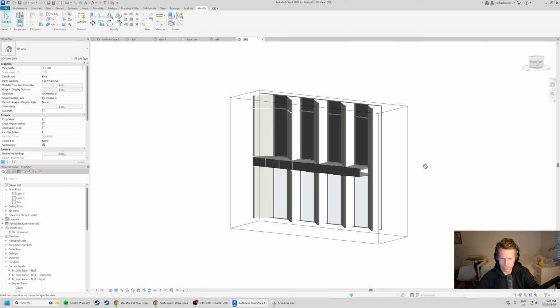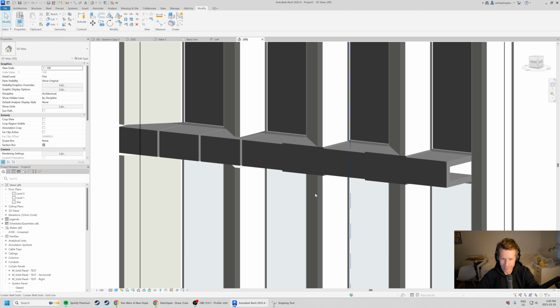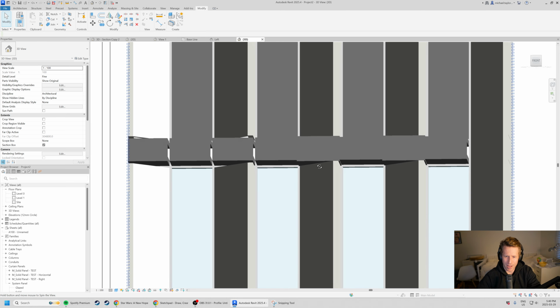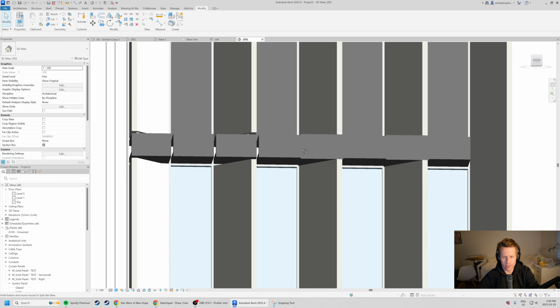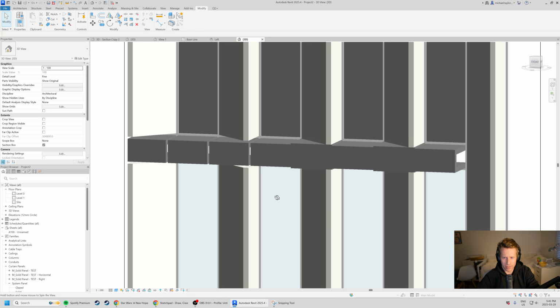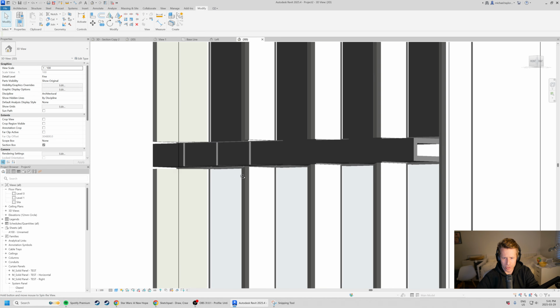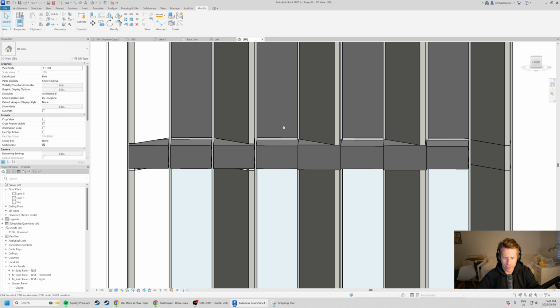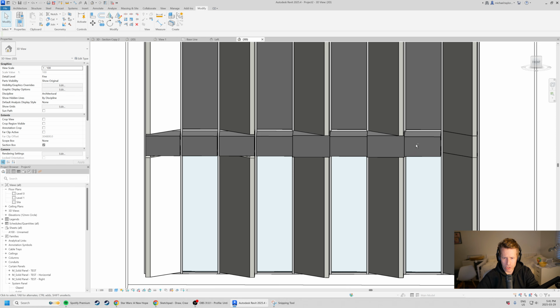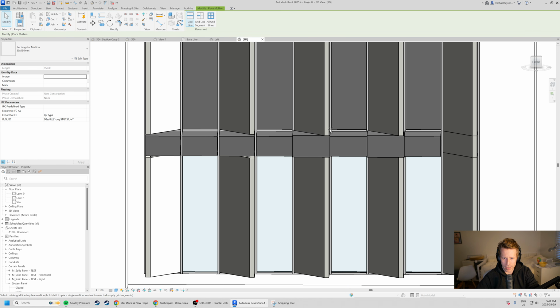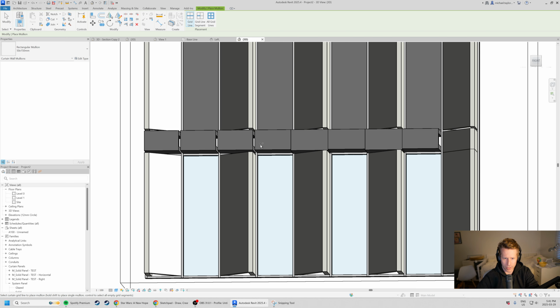So what's going to happen? What's happening right now with Revit is it really wants to see those joints on the edges, because you can see how it's kind of starting to interrupt the flow. So if I come back in here, I'm actually going to go ahead and reattach my mullions, right? So we can kind of have the same pieces come across.